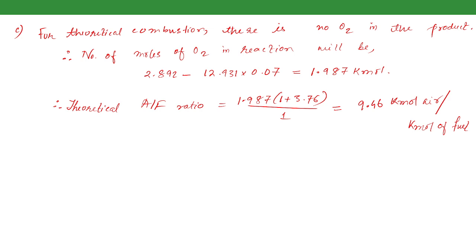Now, therefore, percent theoretical air is 13.77 by 9.46, which is equal to 1.45, that is 145%.